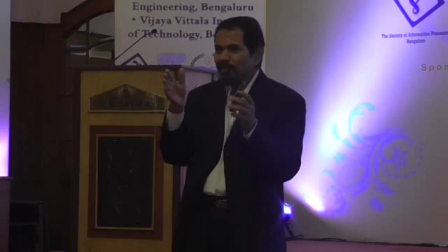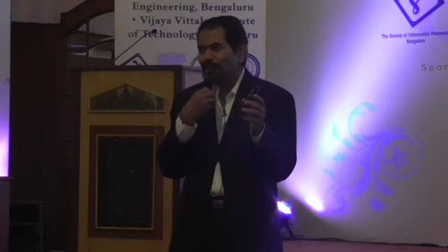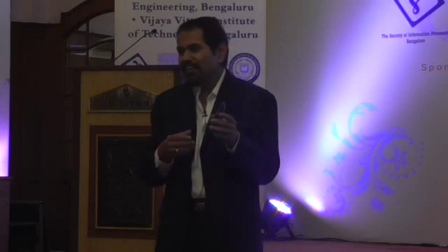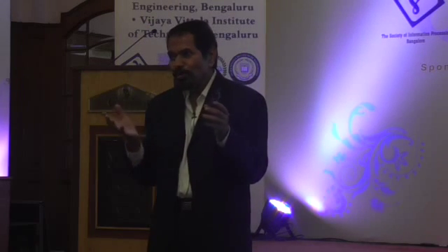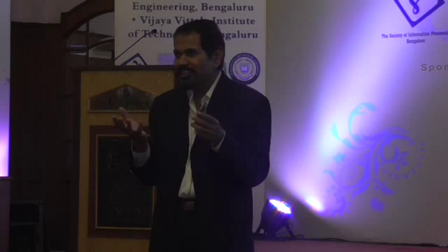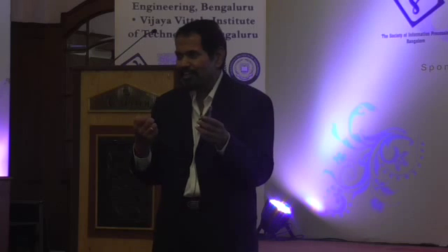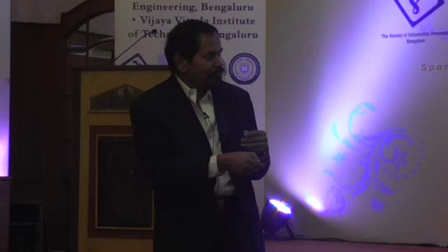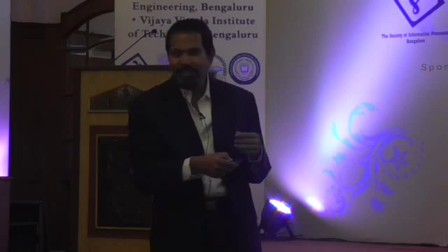I can change my beam direction and concentrate only on this direction, such that the people sitting here can take advantage, or I can speak at a lower volume, or I can increase the range, or I can increase the capacity of the system. So that is the beam forming technology which can be used with phased array techniques, which is available in radar, and that has been borrowed here. So it's a combination of MIMO and beam forming which gives several advantages.